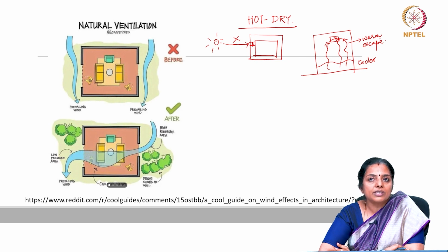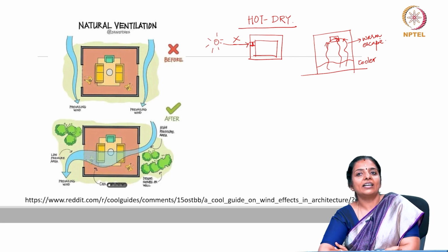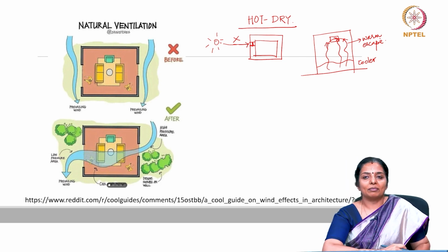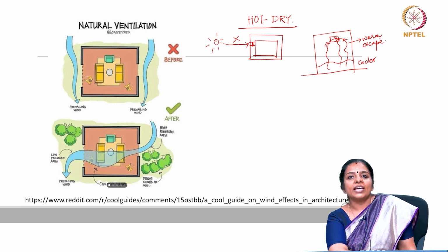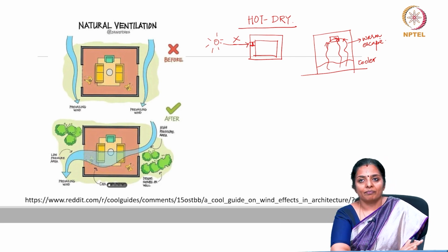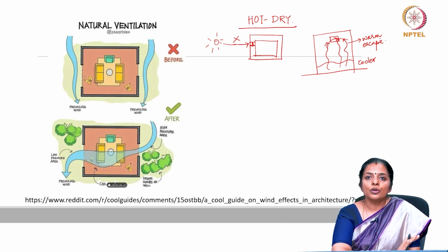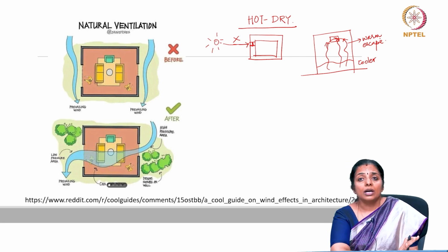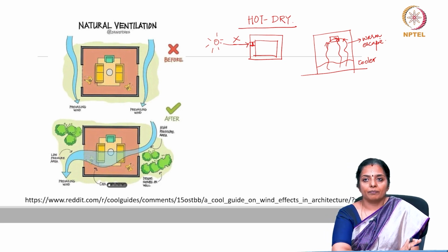In the composite zone, where all the three conditions may occur, which is very complex, window shading holds the key. The shades must cut off summer sun but permit winter heat gain. They should be controllable. The window area would be determined by the duration of each season. If the winter or humid season is long, large windows are preferred.